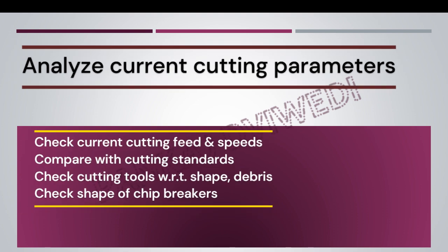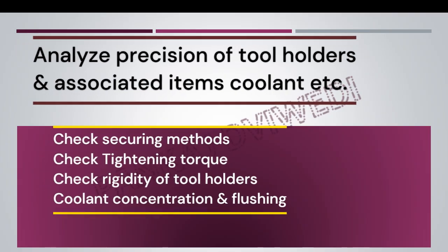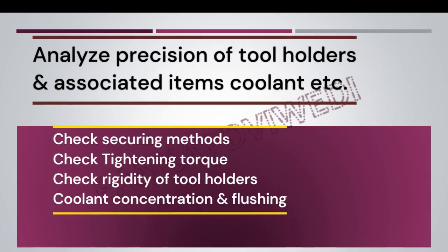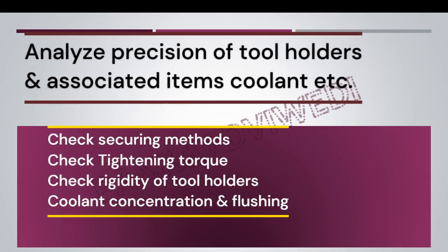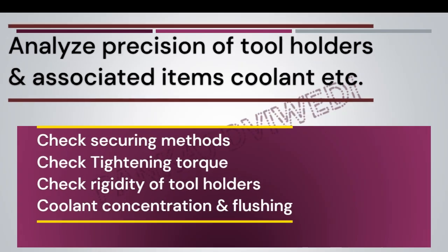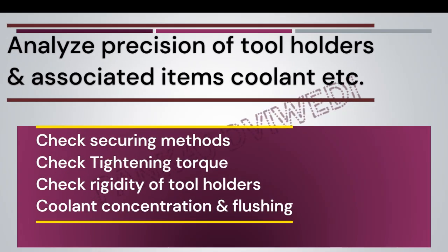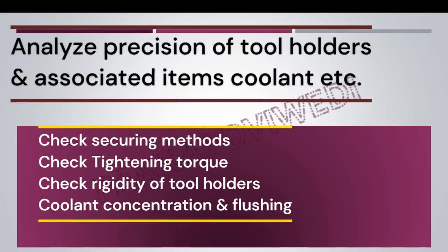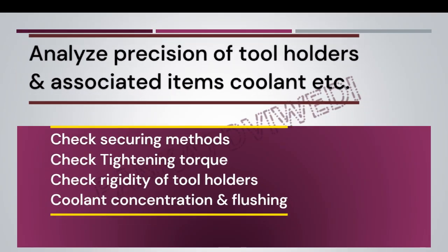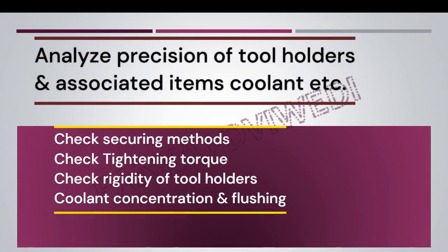Analyze the tool holders. Analyze the mounting methods: is it firmly securing the cutting insert, is the correct tightening torque being used? See the dynamics and statics of mounting.